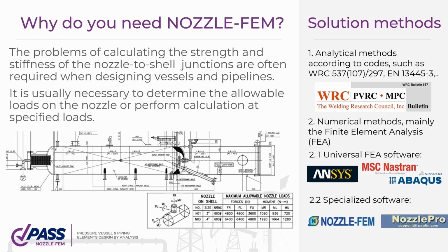There are several methods to solve this problem. First, using the analytical method, as per industry standards such as WRC 537, WRC 107, 297, EN standard, PD codes, and others. Or you can use a numerical method, mainly by finite element analysis programs. All programs that use the finite element method can be divided into two classes, universal and specialized. You can use universal software such as ANSYS, Nastran, Cosmos, Abaqus, and so on. Or you can use specialized programs such as PostNozzle FEM or NOZZLE programs.